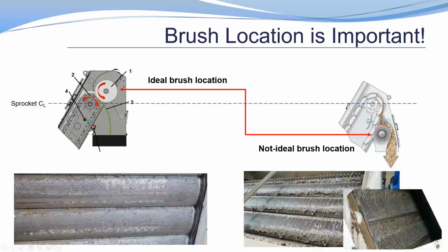The original design, the older designs, having a brush down at the bottom, you can only effectively really clean the top of the panel, or you can put more pressure on that brush, adjust the brush in further. You might do a better job at cleaning the panel, but now you're going to start to wear both the brush and the panel much more quickly. So with a proper brush location, you get a much more effective cleaning on the backside of that panel.